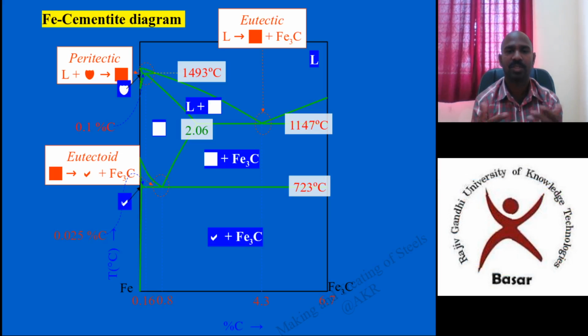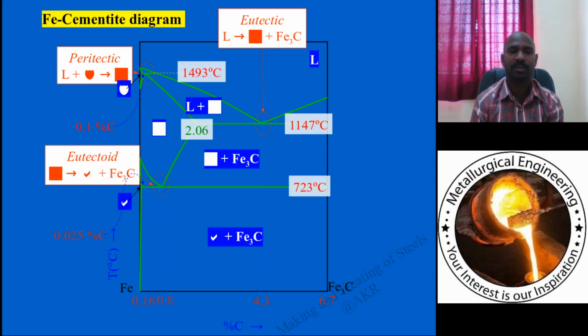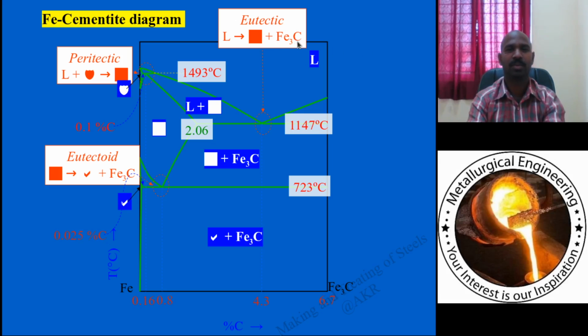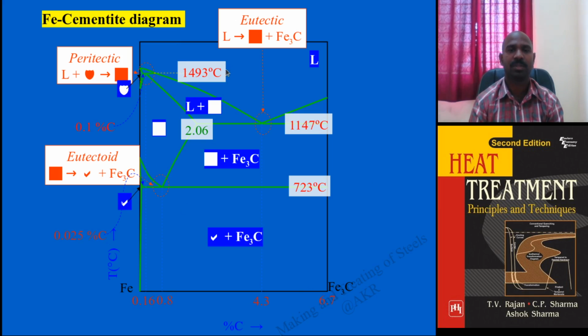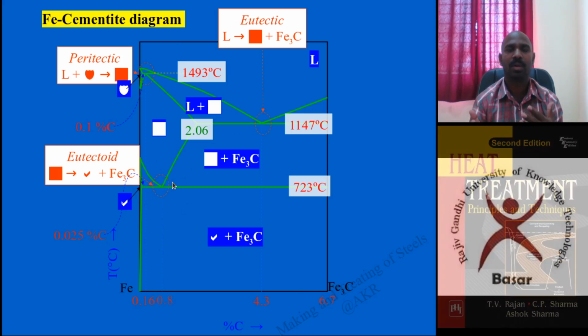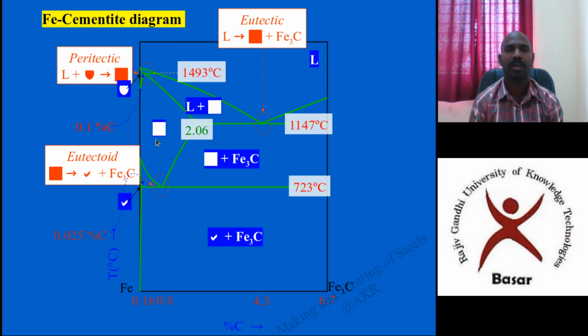And as you know from the physical metallurgy topic, this is the iron cementite diagram, where cementite is nothing but Fe3C, iron carbide, or the iron carbon diagram. There are various names which are broadly followed. This is the iron and iron carbide diagram. This particular point is the eutectic point and this is the eutectoid point. This is the austenitic region. This is entirely liquid.